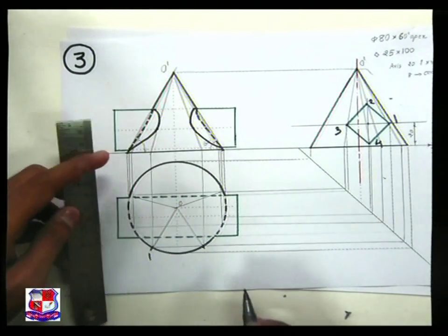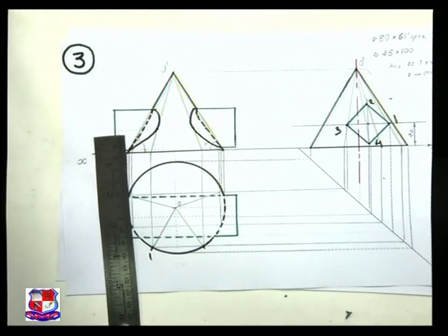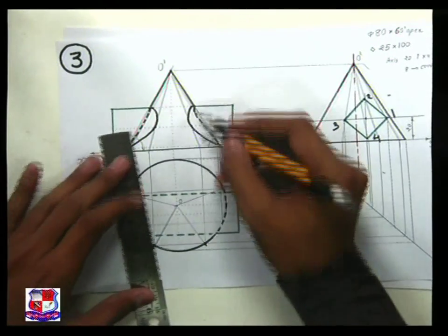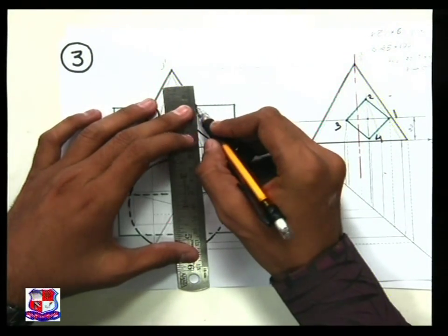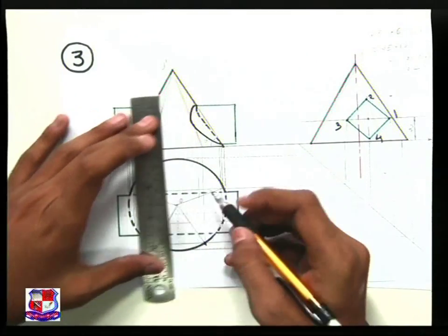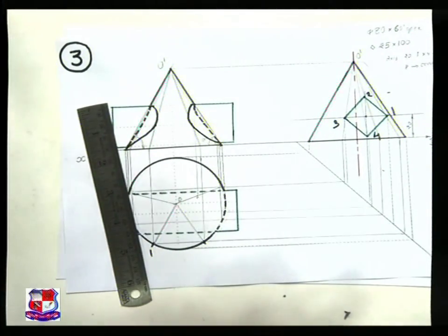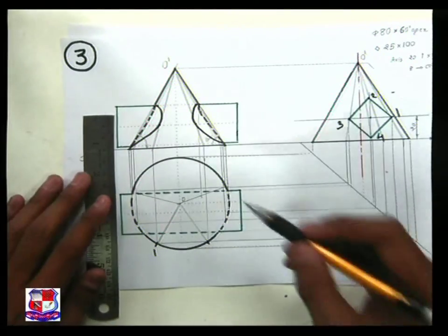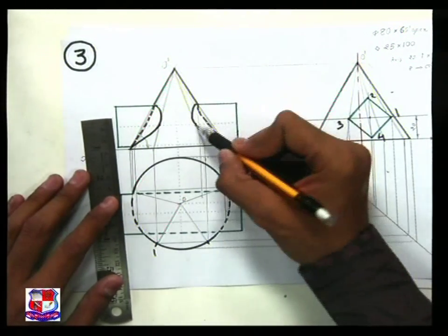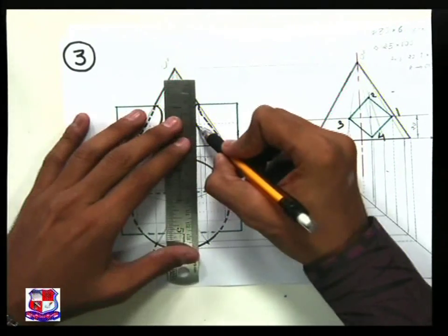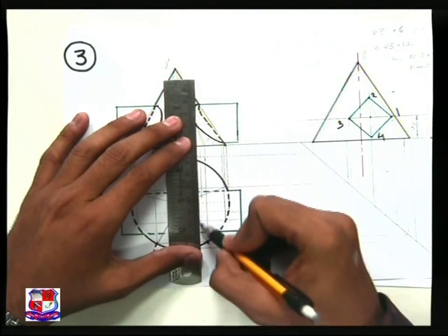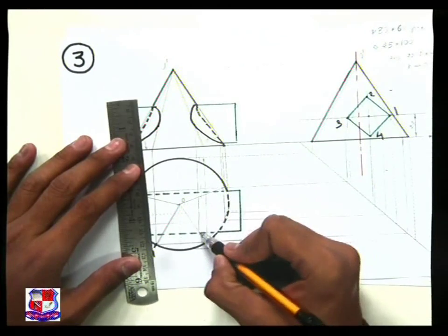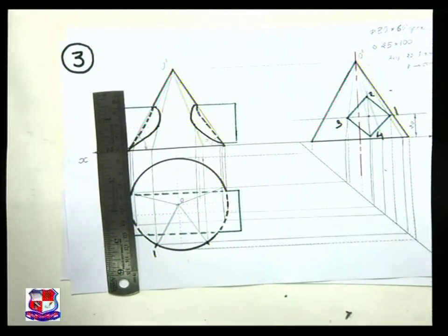Similarly, in top view also we can find the curve of intersection by drawing a projection line from each point, a vertical projection line from this point. It will cut that generator over here. So to find the position of those points, pick up each generator one by one. So this is the generator. Here is point number 1, right? So from this 1, draw a straight vertical line, and it is on generator 1. So here is that point.